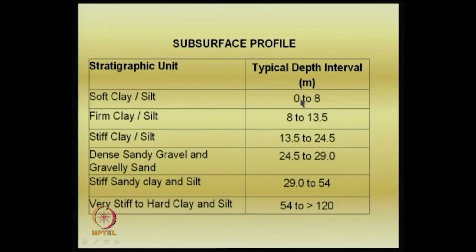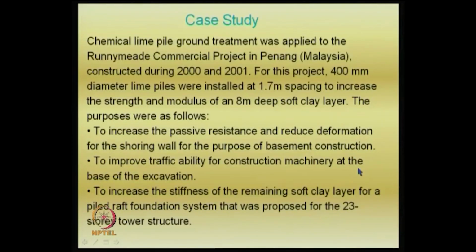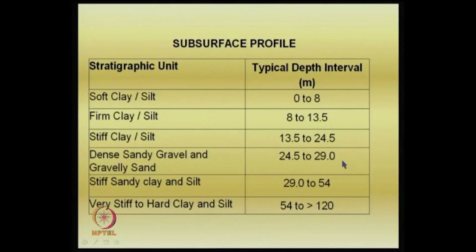So, up to 23 or 40 meters they have got the stratigraphic profiles. 0 to 8 meters is a soft soil, 8 to 13.5 is clay, and you have varieties of materials here, and the depth of investigation is quite good. Like they went to, say for example, 23 meters, which is supposed to be the previous case, yeah, it is a 23 stories, and you can see that the depth of investigation was quite large, about 100 meters, which is quite